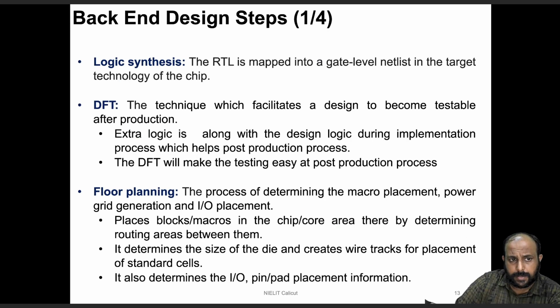So backend design steps, if you look at, the first step could be logic synthesis. In the process of logic synthesis, your verified RTL is converted to a structural equivalent, something called a gate level netlist. This gate level netlist is very subjective to the target technology of the chip. You have a particular RTL design, and we synthesize it for a 90 nanometer technology. The resulting file will be substantially different if you try to synthesize it for a 45 nanometer technology.